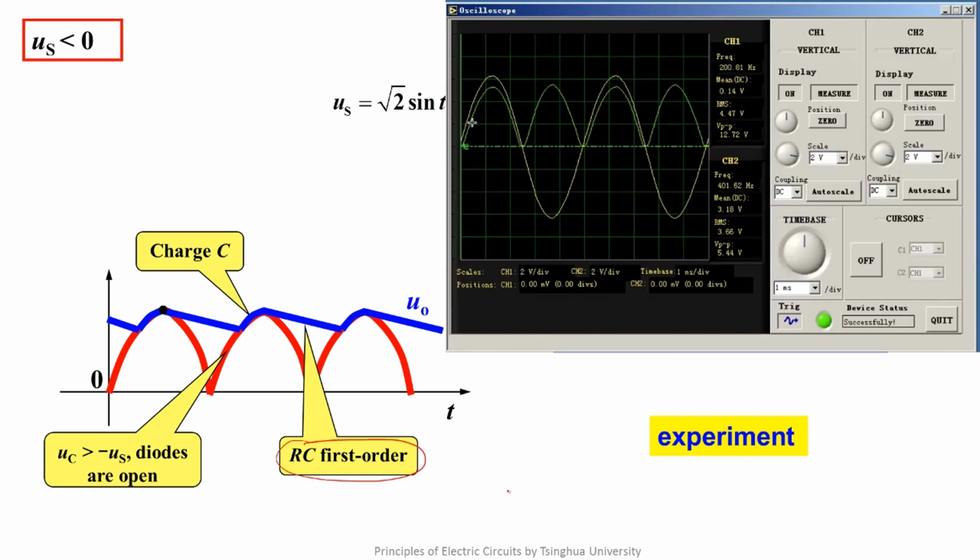Now this is the voltage wave of the input and output without the smoothing capacitor. The output is DC with large fluctuation. Now we switch on the smoothing capacitor. The output becomes smooth and is a relatively ideal DC.